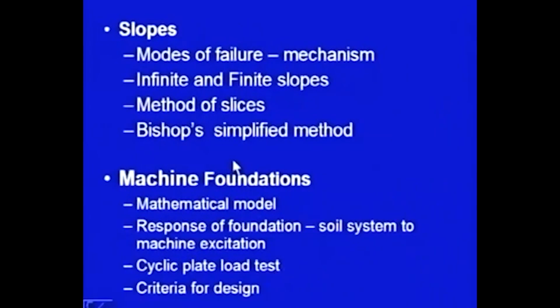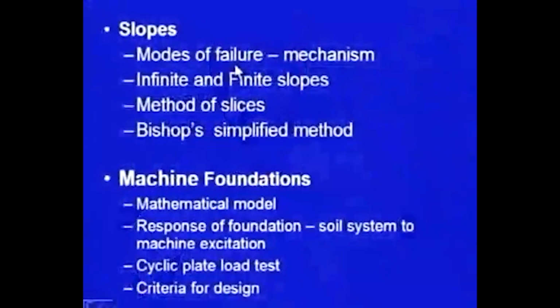Then we will move on to the stability of slopes. Slopes are very important in the hilly regions. They may be man-made slopes, there may be natural slopes. Their stability is a great concern. So, we shall be discussing the modes of failure, what is the mechanism, how the failure takes place, and then infinite and finite slopes.